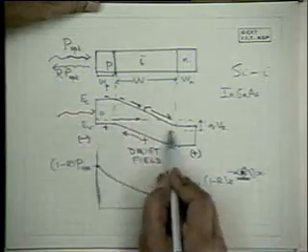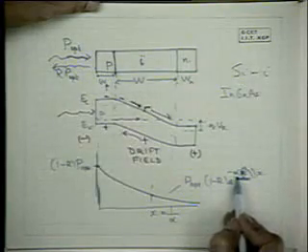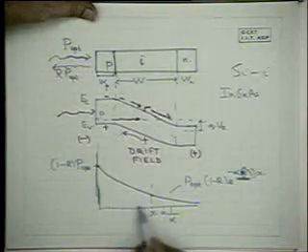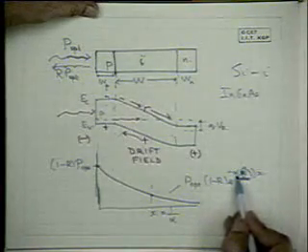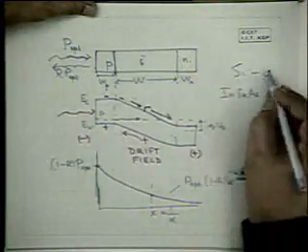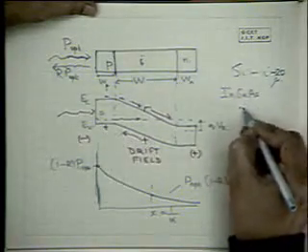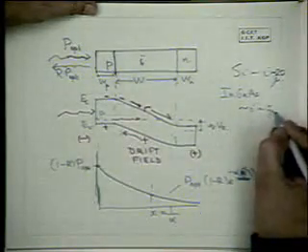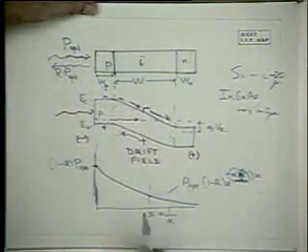So the width of this I layer is chosen taking into account the value of alpha. If alpha is 10 to the power 2, then 1 by alpha is 1 by 10 to the power 2, so that may be a few hundred microns. But if alpha is 10 to the power 4, then 1 by alpha is of the order of microns. So in silicon, the I layer could be something like 20 microns. For InGaAs, the so-called I layer could be of the order of 2 microns, depending upon the optical absorption coefficient at that particular wavelength.